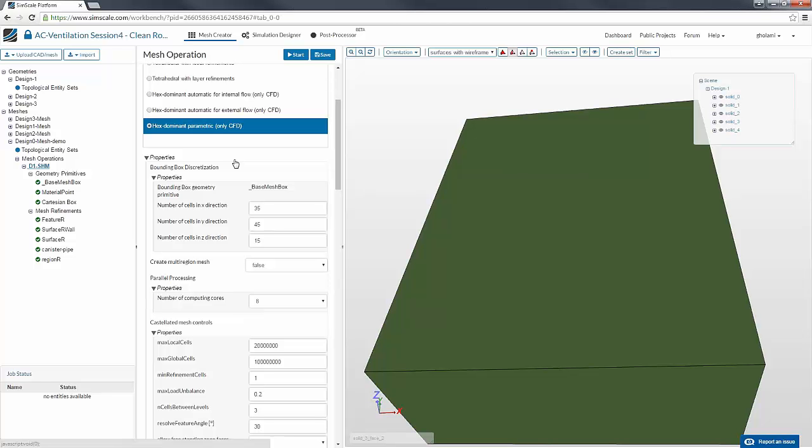It's not the final size of the mesh, it's how we initially create our mesh and work our way by refining it. Normally we automatically create these numbers, so unless you want to use larger numbers, you don't need to really change these. Here's also the number of the computing cores. This also is set based on an estimation of the final number of the cells in our mesh.